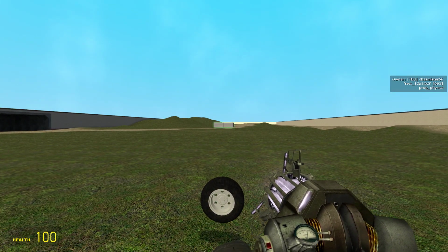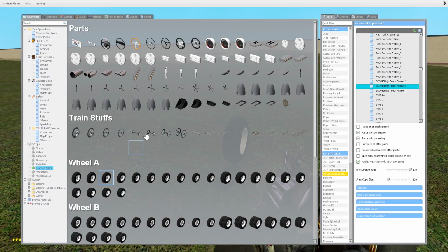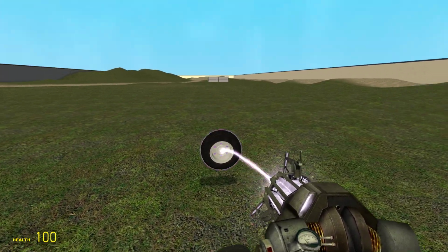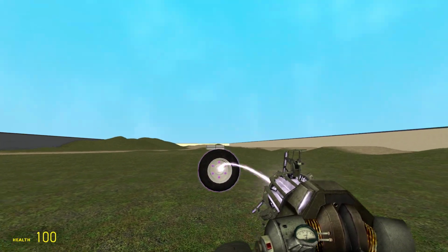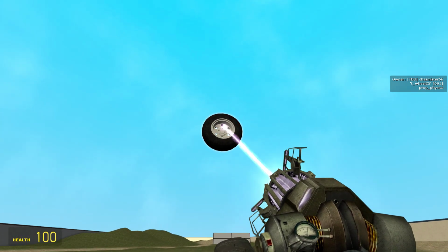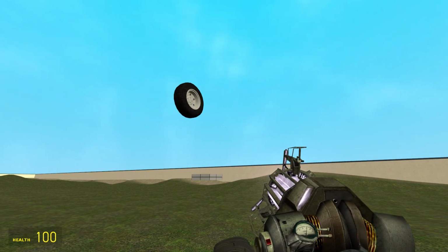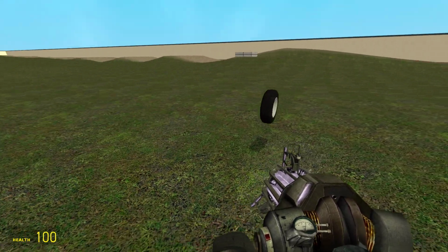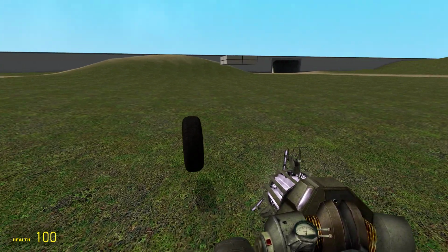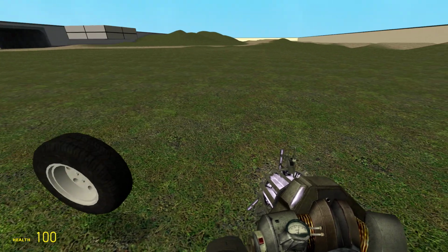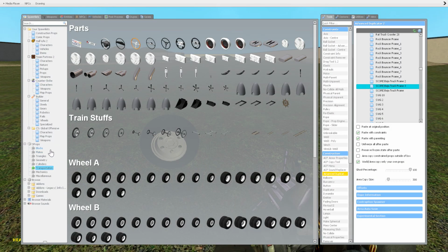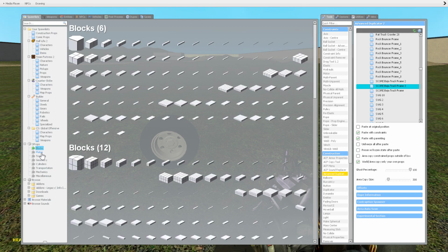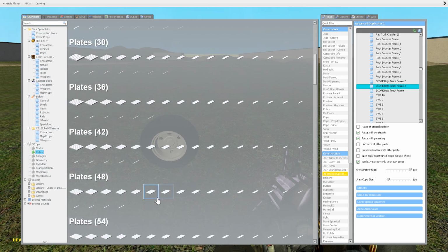This is still used by some people today in the community, but the problem with this is once it gets to a point where the hydraulic doesn't like it, it will break above, and then it will be reversed suspension, and you don't want that. And that can be fixed with rope limiting, but the problem with that is, well, you're going to limit your suspension travel.